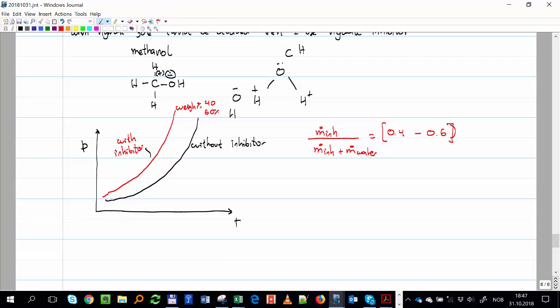That means if I'm producing 1,000 barrels of water, I have to add how much? 1,000 barrels of inhibitor, right? If we say 50-50. So that's a lot of inhibitor that we have to add. Okay, if I'm producing 1 barrel, my life is fine. I'm happy. If I'm producing 1,000, I have to inject quite a lot of barrels per day to be able that my line is here, and in the expansion in the pipeline from P in, T in, to P out, T out, I don't reach the hydrate zone, okay?